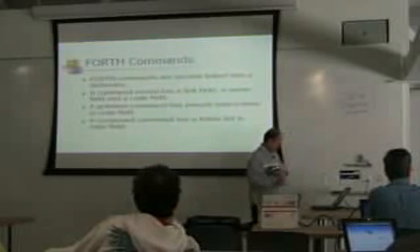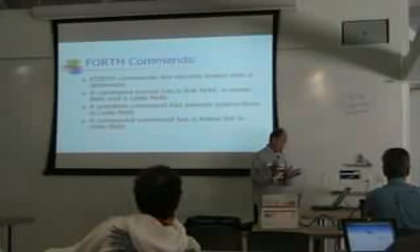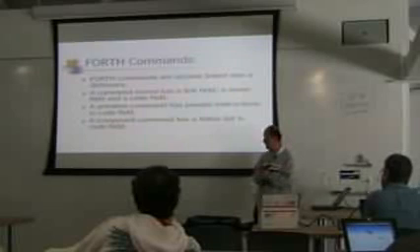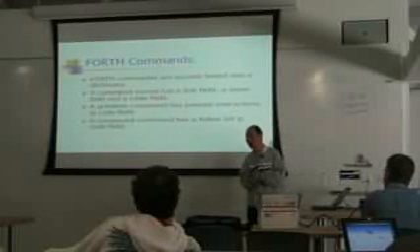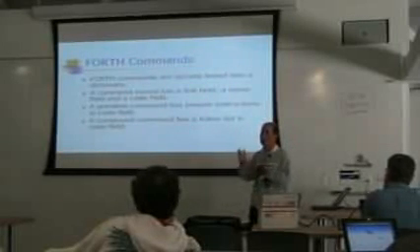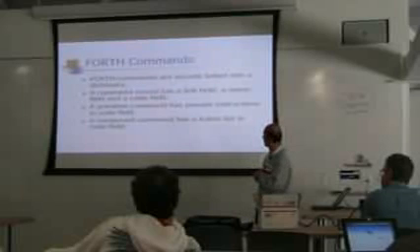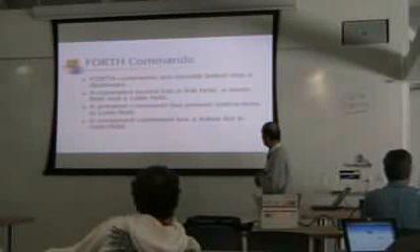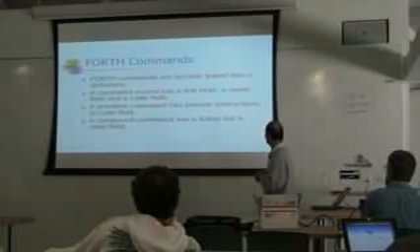Of course, eForth commands are linked into a dictionary, and since we have a unified memory model, we have a set of instructions which can access both memory areas, so there's no problem growing the dictionary into RAM. The commands have a record: the link field, name field, and code field.